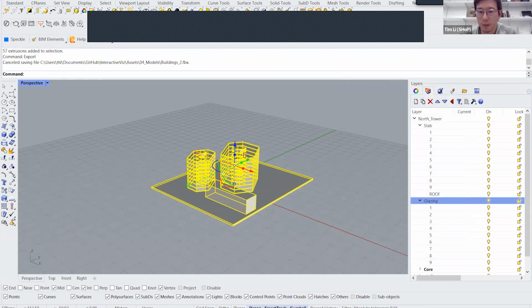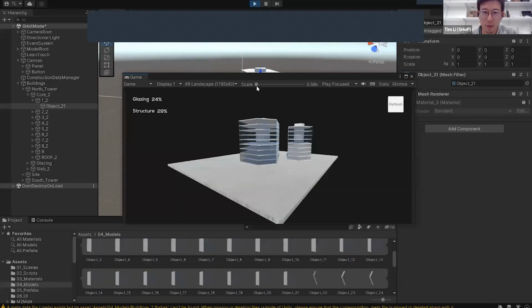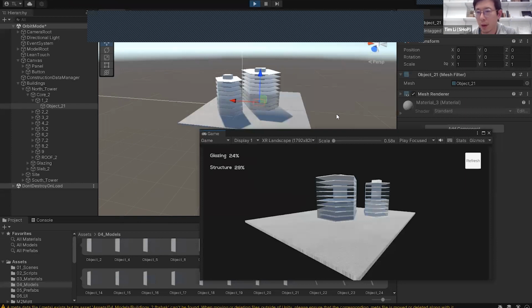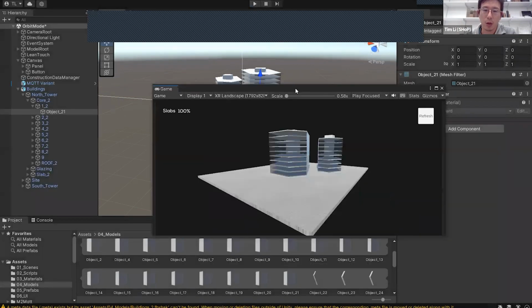Actually, yeah, that should be the case. That's also one other thing that's less tricky about FBXs, because with OBJs or some other file formats, the X or the Y and Z are flipped, so you need to make sure the orientation of the model is right once you import it.